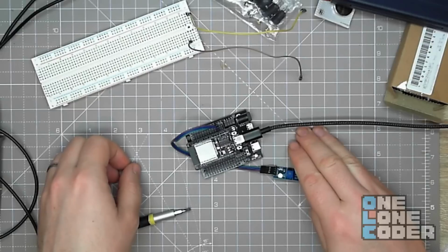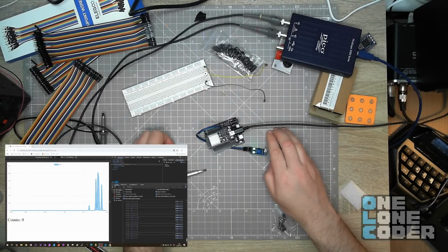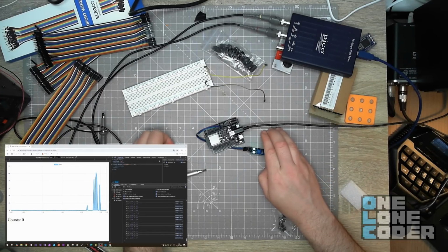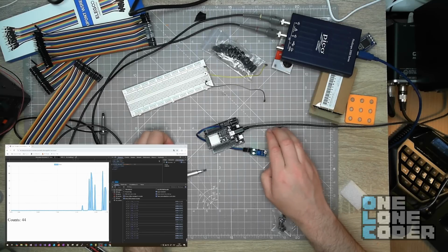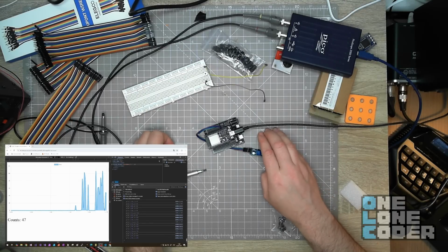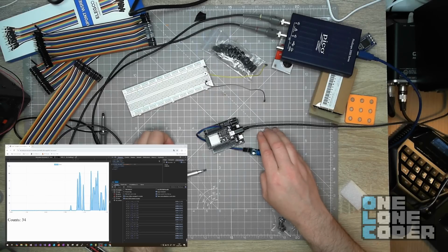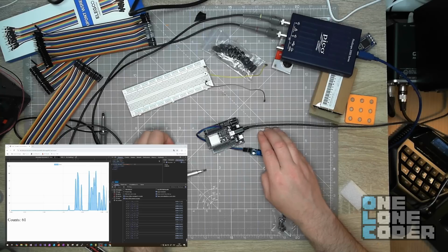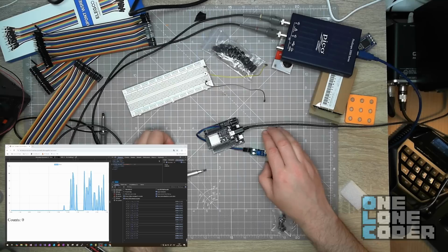And if I cover up the sensor, we can see one of the LEDs going out. More importantly, as I cover it up, we can see that the graph is also counting how many times I cover it up. In fact, it's actually counting loads of times. Looking at the values on this graph, we're seeing 29, 67, 34. That's because the threshold of this comparator has absolutely no hysteresis whatsoever.